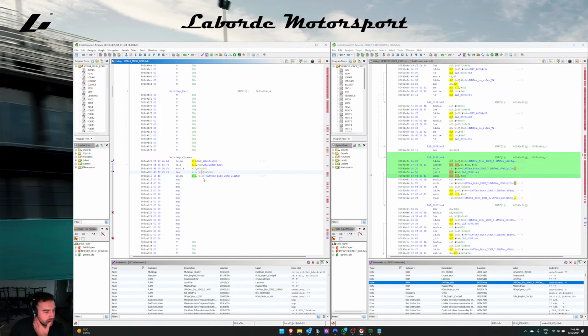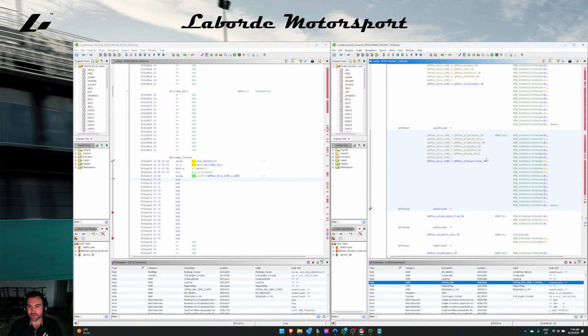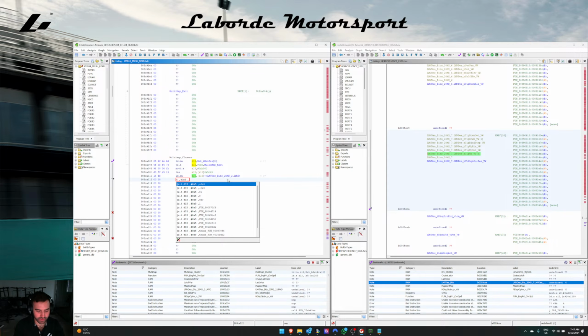So we're going to load that into data register 15, and then from here we're going to start checking some conditions. We're going to check whether the cruise control stalk is being tipped up or tipped down, so we'll check position 1 and position 5. I'm going to go jump.t bit position 5, and then jump to a certain address where we're going to be doing some passing.